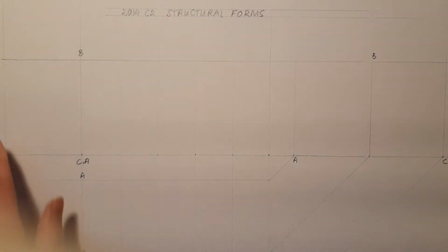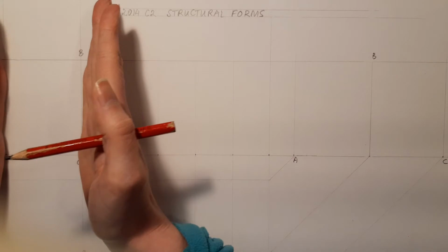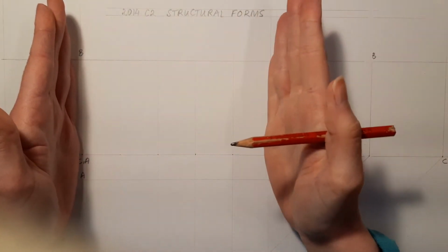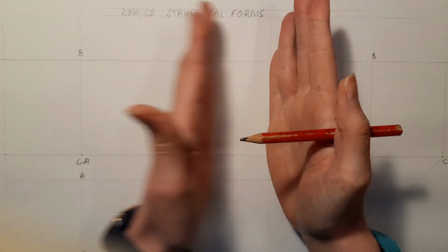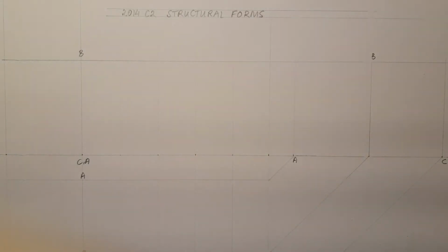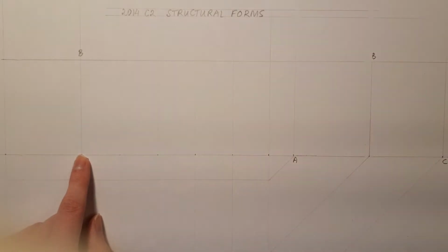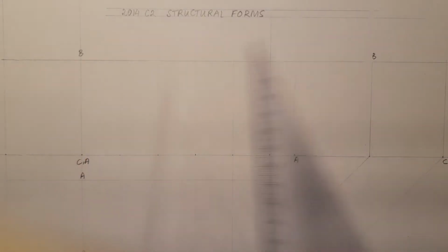So the first thing I'm doing is a parabola over here. As you can see, I've measured out the 60 and the 150, and there were 5 spaces in the middle, so I went 30, 30, 30, 30, 30. But we'll start off with the measurement anyway. So I've this divided up into 5, so I'm going to divide the side up into 5. So you're going to use line division.